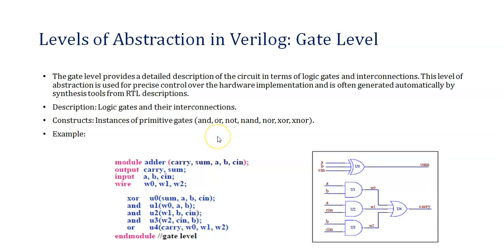There are a total of 8 gate primitives present in Verilog. Other than that, there are 12 primitives. In the coming session we'll be addressing that. As I told you, for writing a gate level modeling style Verilog code, you should know the gate level structure, then and only then will you be able to model it.